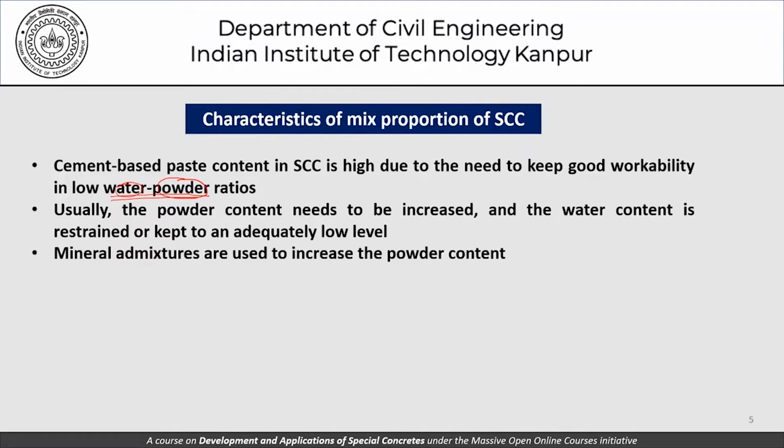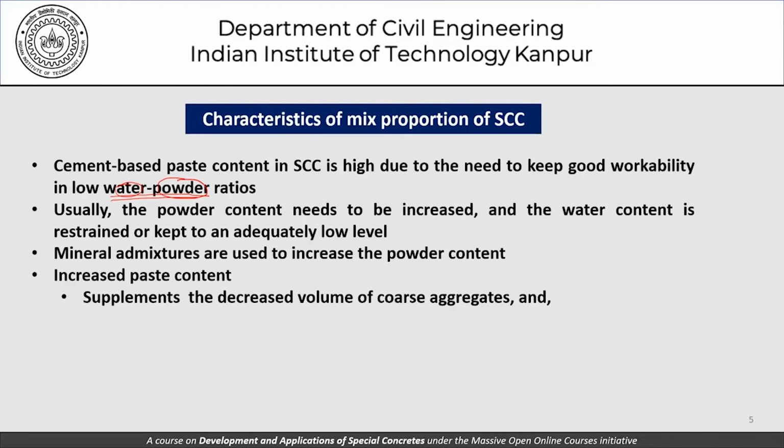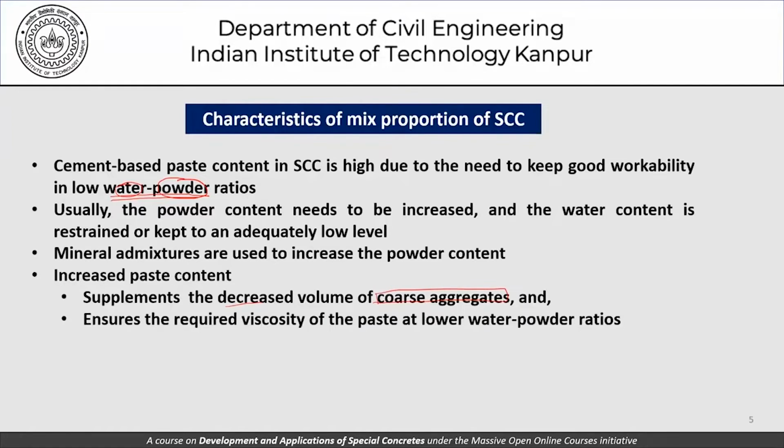Mineral admixtures are used to increase the powder content, which increases the paste content, and if that happens, it leads to a decreased volume of coarse aggregates and ensures the required viscosity of the paste at the low water to powder ratios.